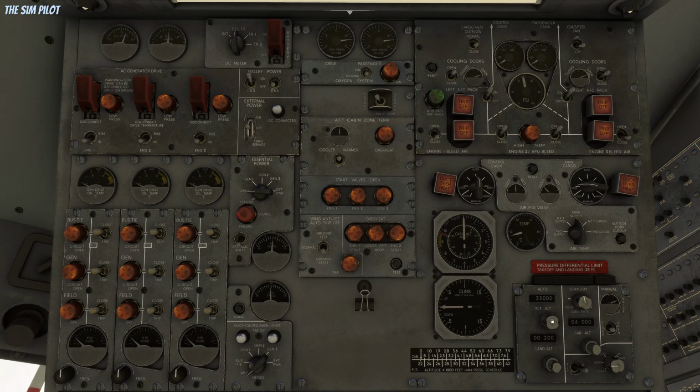I don't think I have done the pressurization panel in this episode because I started fresh from scratch, so let me do that because I know I have done this in the previous video. We are cruising at 29,000 feet, that's 3.2, and this is just a recap for those of you who haven't seen the first episode. What you need to do is set your cruising altitude, set your landing altitude, and then set your cruising altitude based on this placard over here, based on your cruise level. So if it was 30,000, that's 3.6, so that's 3,600.